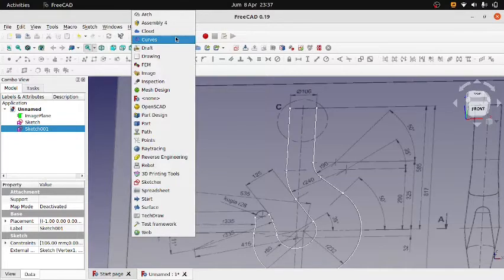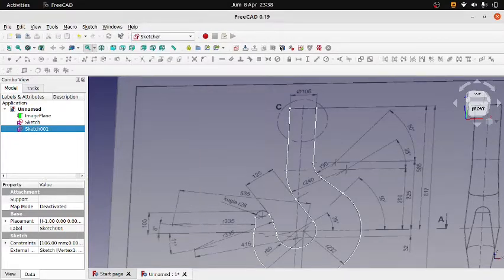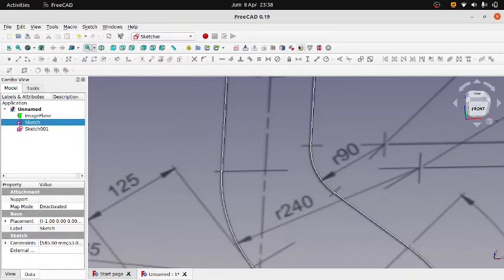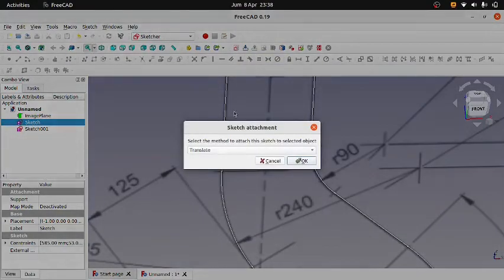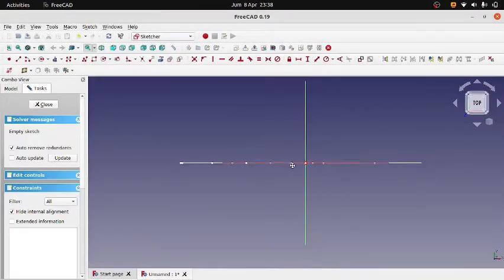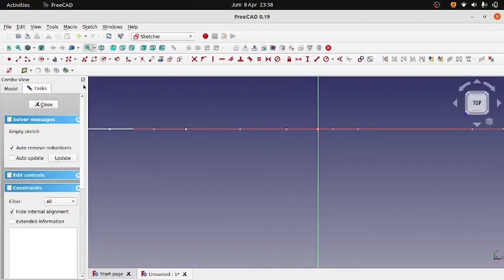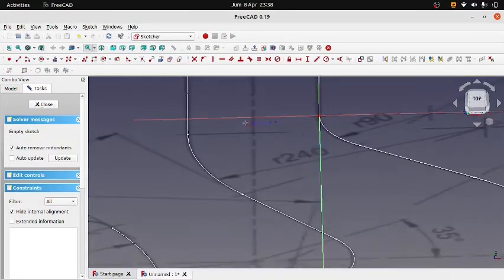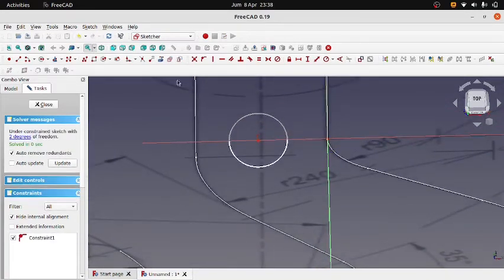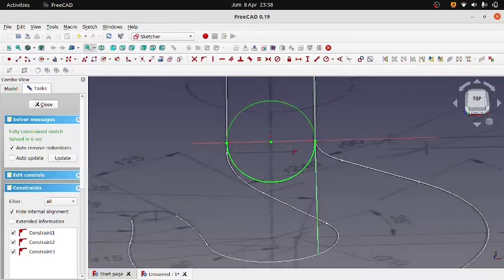The next step, we need to draw some section profile of the crane hook. So what we need to do is add some sketch using this point as a reference. Okay, good sketch. Using translate means that the plane we use for drawing is offset from the zero origin. Okay, next we draw a circle as the section profile and use edge link to project another curve that will be connected with our profile.